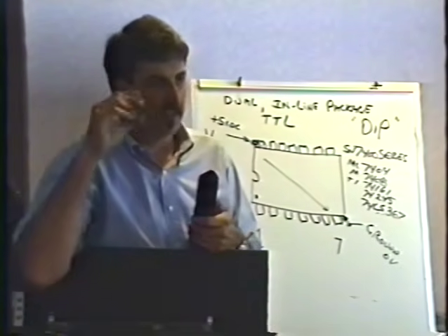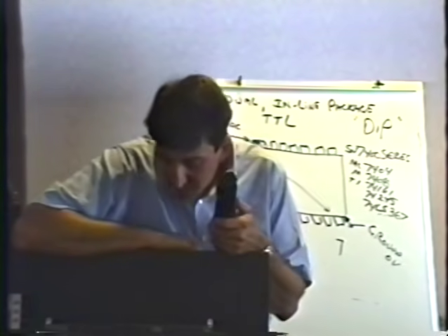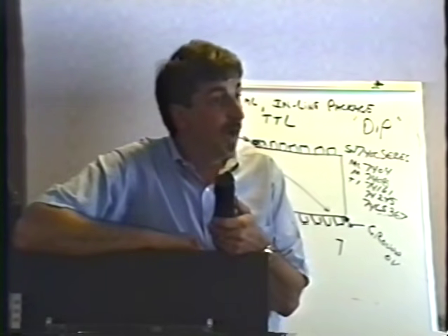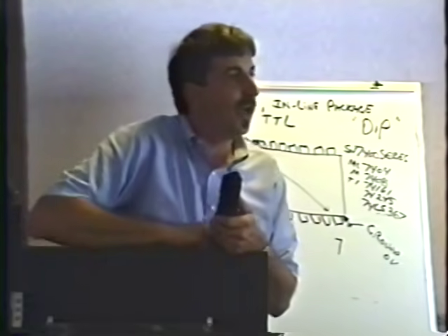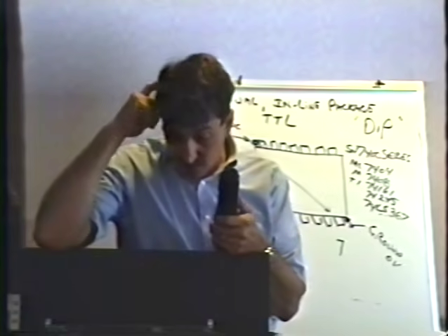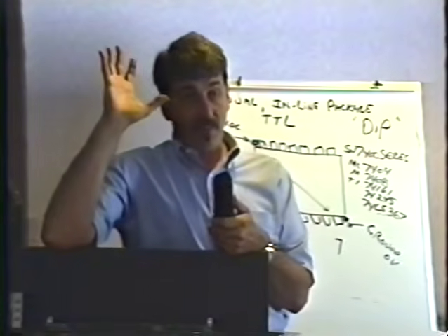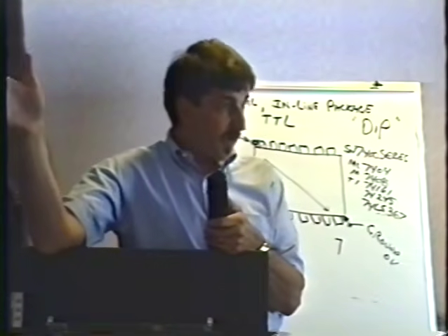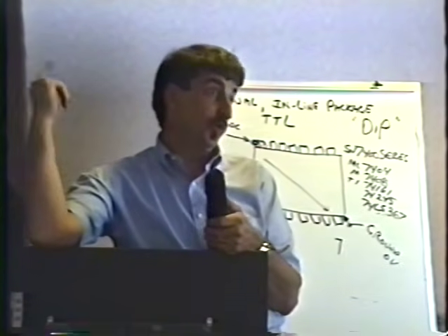The test does a little self-test dance that it does, checking its internal stuff. Fired right up. Just to verify, Claude checked it across this chip right here, 5.09 at this point. Fine. Works great. This monitor does have a problem, and we'll talk about it Thursday. It's real bright on one side and real dark on the other. It has a typical capacitor failure. It happens to be capacitor C702.